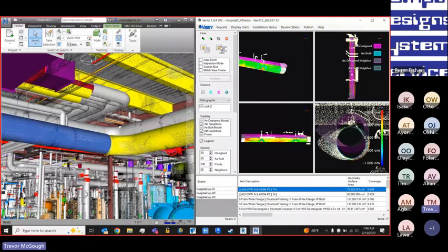This is about 17 items, but if you can imagine doing like 700 items, this is quite literally how I can convert from as designed to as built inside of Navisworks to get accurate models for clash detection and coordination. So quite literally, I can convert at a click of a button.